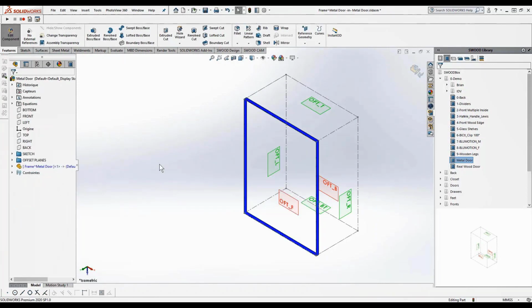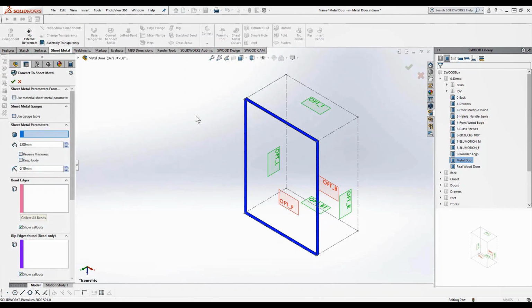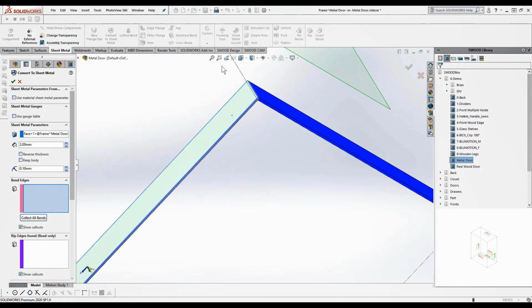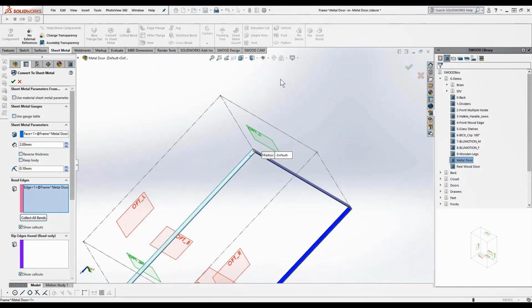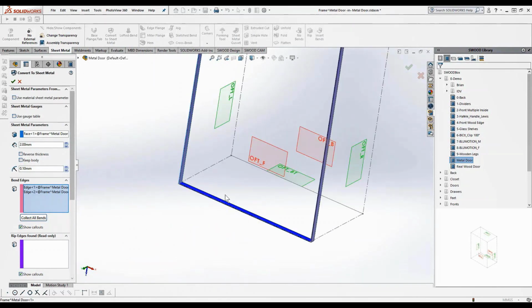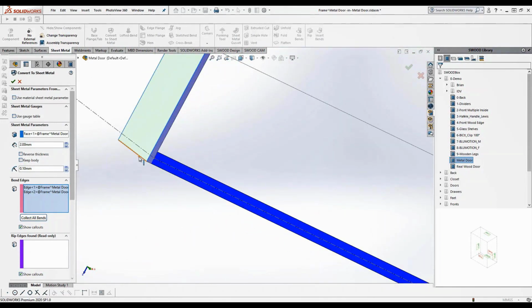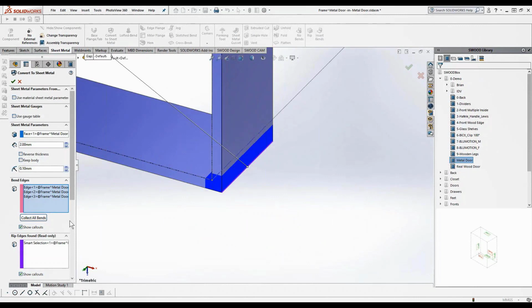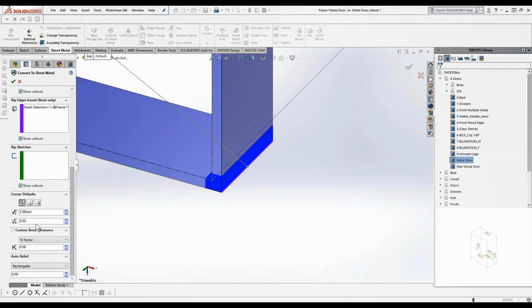Well, the second step, we will change directly this rectangle to a sheet metal part. We can easily extrude this one by giving some thickness. And here, with the sheet metal function, we can easily convert the body to a sheet metal part by clicking on the bend edge, and it will automatically generate the calculation of the sheet metal part. Of course, you can easily manage the extremity, give it the covering or the covered side, or give it the offset distance. And now the work is done.